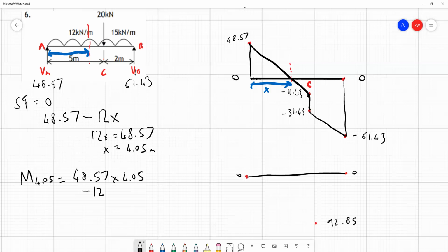We get the total force from the distance we're considering. So this is just over the 4.05 meters. And then we consider this to be acting halfway along that 4.05 meters. So that's times 2.025. So just indicate that in green. Effectively, we're saying the UDL force relative to this point X is here, and that is a distance of 2.025.